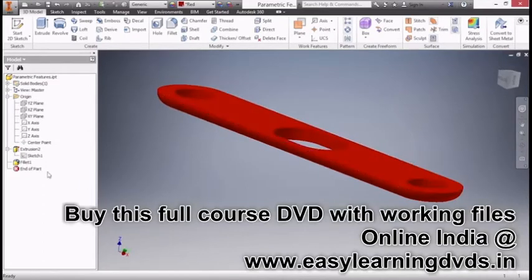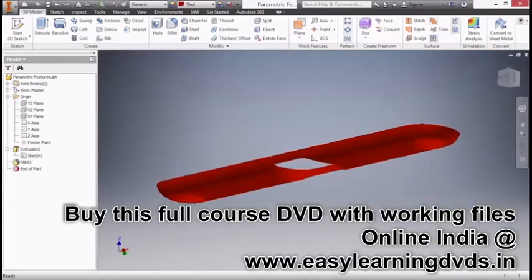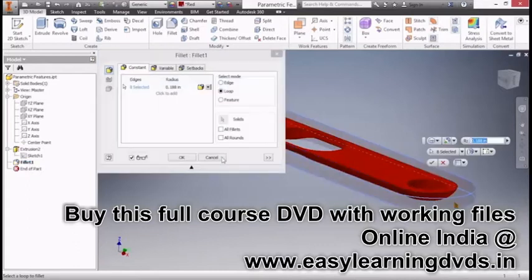I'm going to go back and double click on fillet again. And let's say I change it to 0.188. I'll approve that again, and it still is creating a very inappropriate fillet for this type of design. I'll go back to fillet again. And instead of trying to just put any old value in that would work under one circumstance, maybe I'll put a value in that would work under all circumstances.